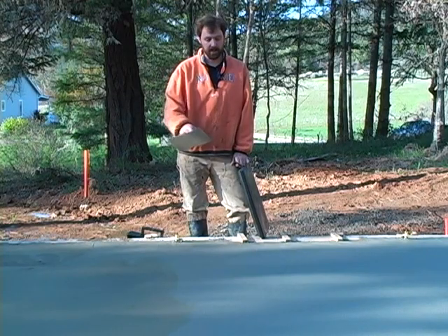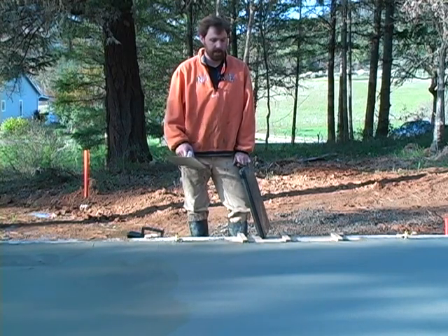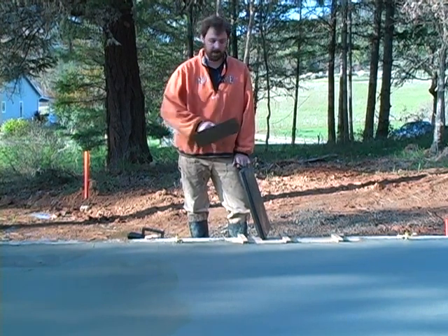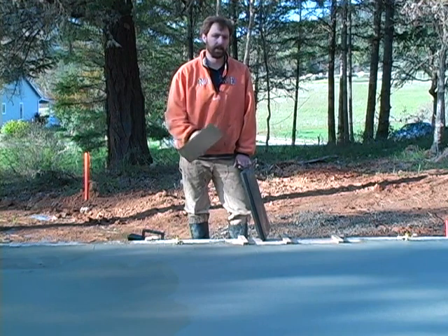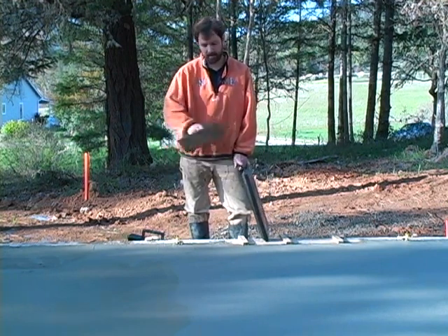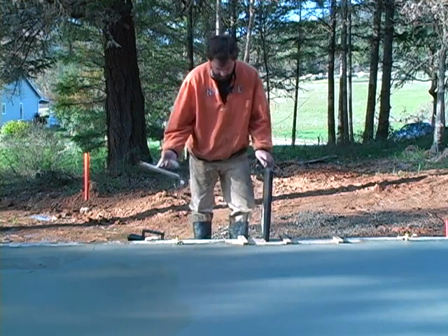The final step is to use a steel trowel. Now it's important to know exactly when the slab is ready for you to get on it in terms of troweling it out. If you get on too early, it'll squish all over the place. If you come too late, then you can miss it and it'll be too hard to work. So you just want to keep an eye on it.